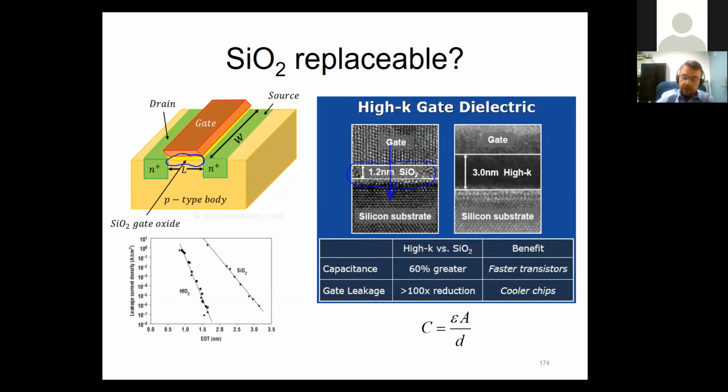You change it with what we call high-K dielectrics to put a little barrier for the electrons, and these high-K dielectrics will withstand these electric fields and will stop the electron conduction from the gate down to the silicon. If you stop that, you will also prevent the leakage of the current. The current won't be leaked away, so you consume less and less power.